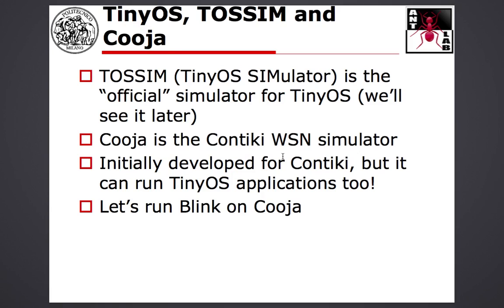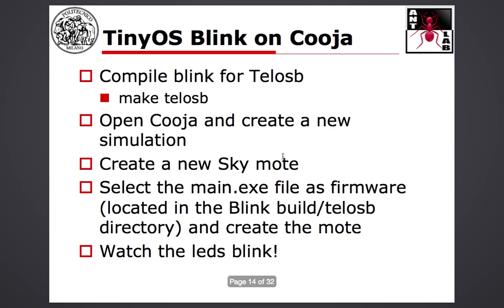So what we will do today is basically run this Blink application that we have compiled in the Cooja simulator. Okay, so we will actually see simulated nodes, and we will see that the LEDs are blinking. So in order to do this, we have to compile the Blink application for TinyOS. We have just done it, okay, with make.